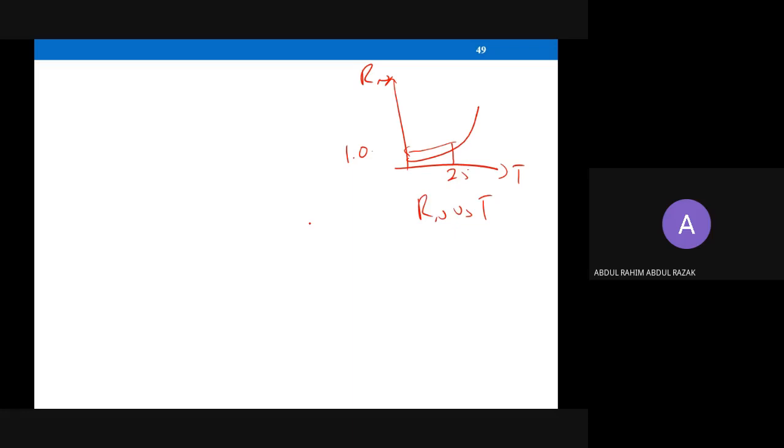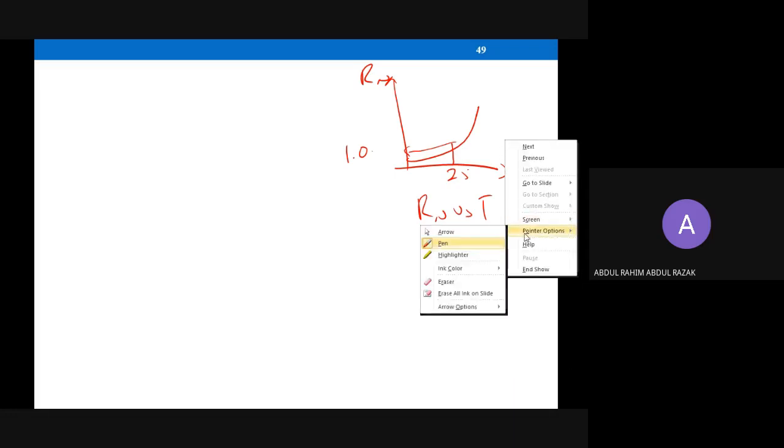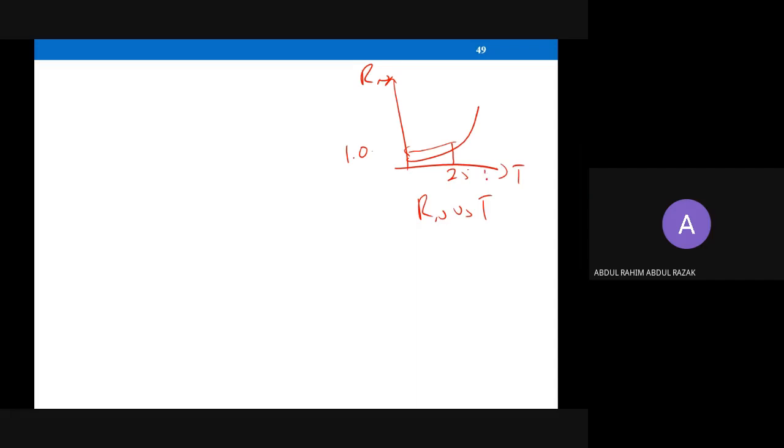Now, if you want to use it at the maximum temperature, which is 175 degrees C, the normalized value is no longer 1.0. The value will be here; if you refer to the datasheet, it's around 3.2 or 3.1, so around 3.1. We are not looking at the exact value, but at estimation and projection.